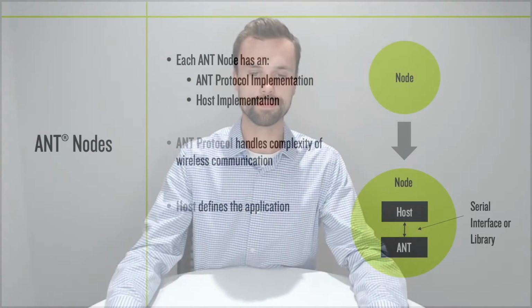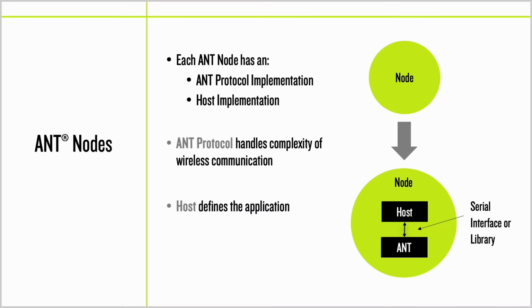Okay, so we've talked about ANT at a high level and established some of the possible use cases. The next several slides are going to do a deep dive into how ANT works and explain how some of the various ANT features can be used to build a solution for your specific use case. First, we will be defining an ANT node. An ANT node consists of a host and ANT protocol implementation, often separated by a serial interface.